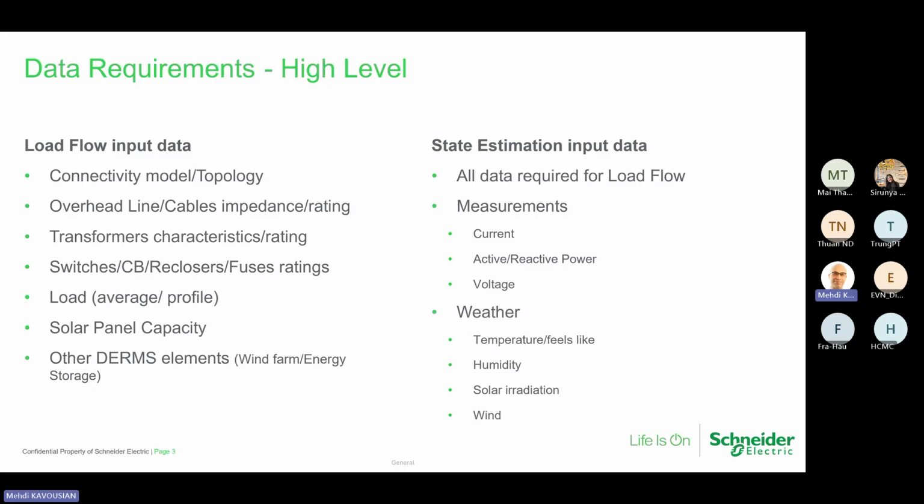Okay. So how do you do that? In GIS or other sources of information, they know, for example, this conductor has this cross section, is aluminum or copper or whatever. They go to the catalogs, or use some calculations to calculate, for example, resistance. For reactance, it's basically the spacing between the lines. There are some applications that you can use, and use some guess. Better than nothing, right? And then use the length.